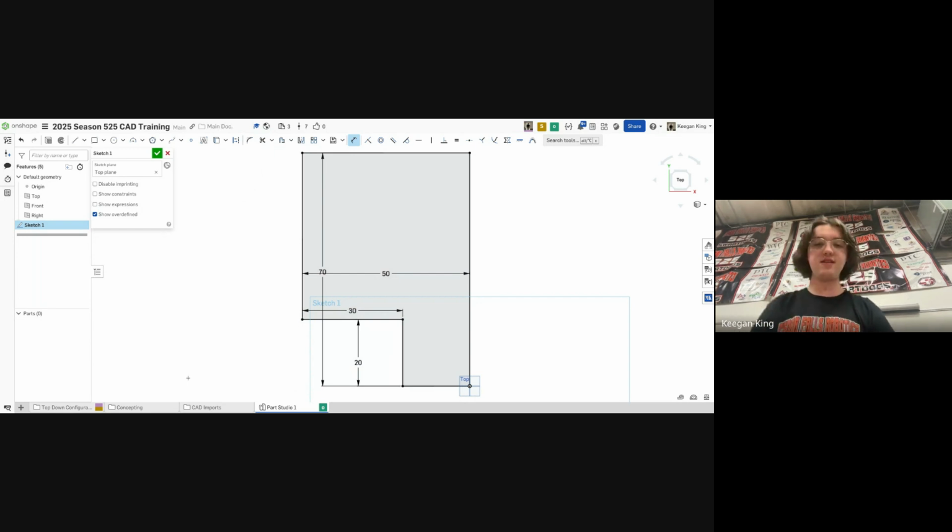Okay, so that redefines it. So now we have that cutout in the bottom left corner. And then we have a 10-inch rectangle here that will end up being extruded out. So I'm going to start another line by hitting L. I'm going to go to this corner, click off really anywhere, hit 10, and then I'll go across and get it horizontal and vertical is fine, or you might be able to get a constraint or a horizontal line like this. So that gives me that rectangle that we're going to extrude out of this shape.